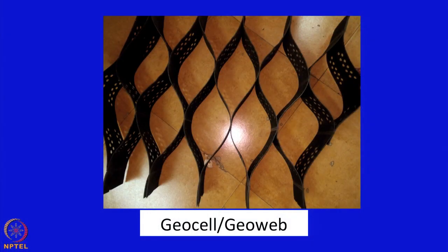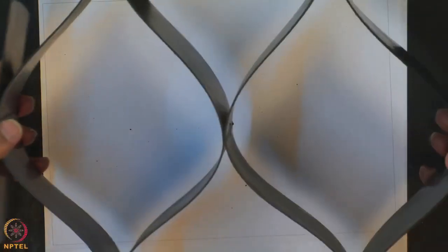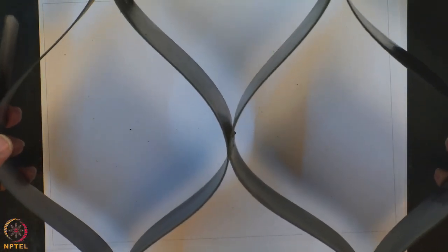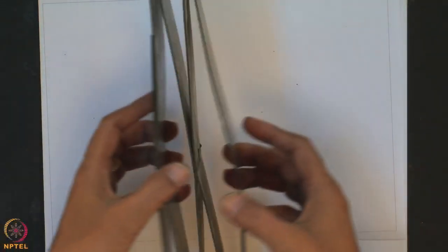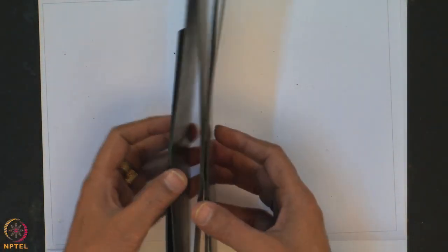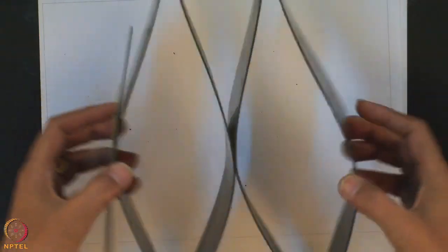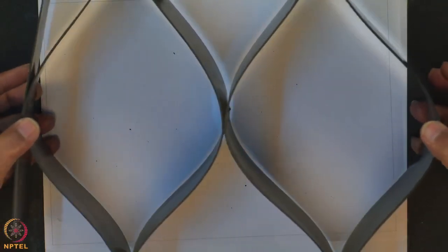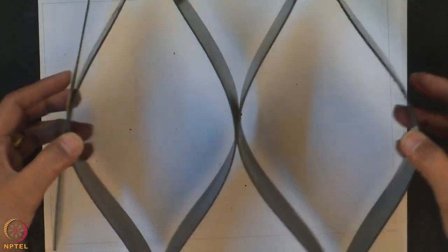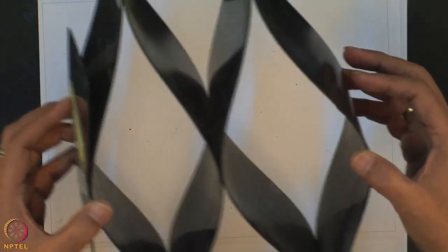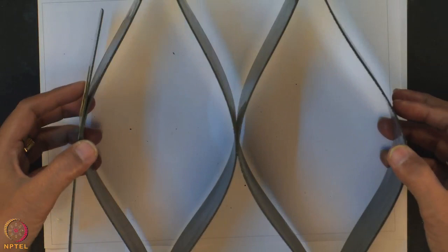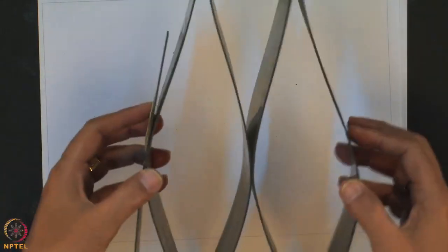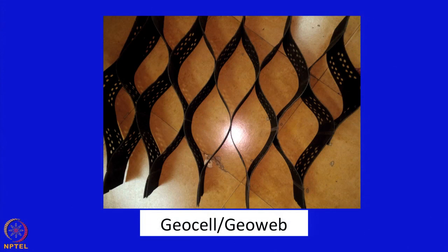This is another material which you call the geocell. So, this is the geocell, this is a 3-dimensional hexagonal structure. So, this geocell can be collapsed, it can be expanded and it can be filled up with defined types of filling material, gravel, sand, and place it and compact it. You can construct the road, you can use it for the slope, you can use it for erosion control. It has a lot of potential applications of geocell material in civil engineering.